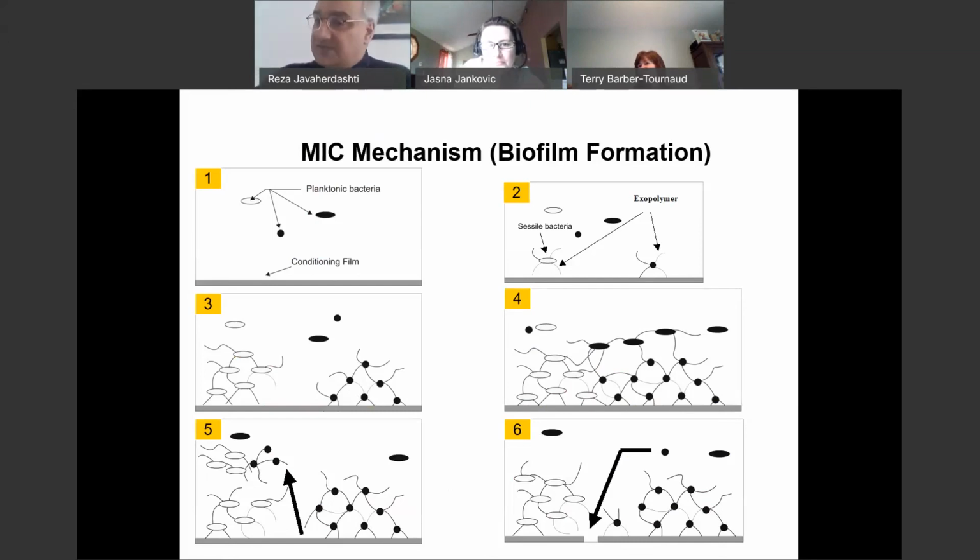The water was basically drifting all that waste, which was a good source of food for the bacteria, towards the jetties, and these bacteria were capable of producing pits in the body of the jetty as big as my head. So when you understand the source of the problem, then it is easy to solve it.